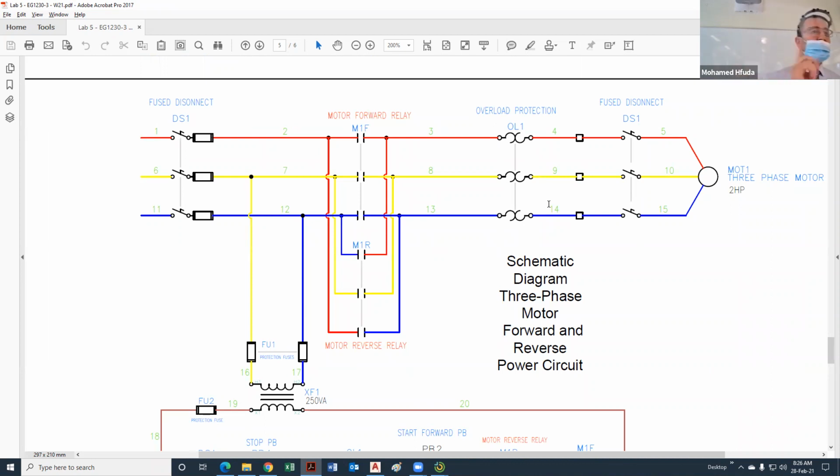Why do you need wire numbers? Well, this is very important for wiring. Because if you look at a cabinet or an installation, you don't just see wires. There are wires and they are tagged with wire numbers. So if you want to do troubleshooting, you want to see, okay, this wire goes from this point to that point. So what's going on? Also during installation, you don't install from memory. Your schematic shows you how to connect the wires from which terminal to what terminal. What's the tag number for that wire? So that's what you see here.